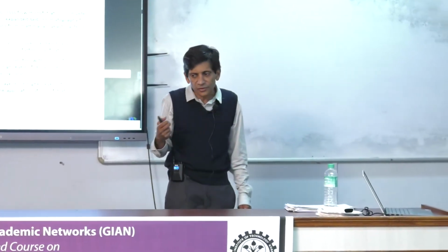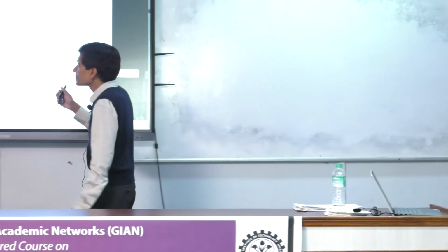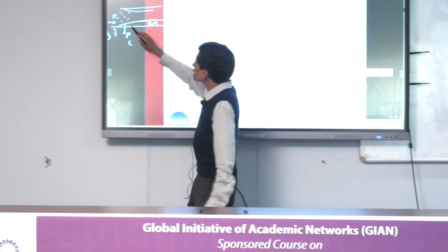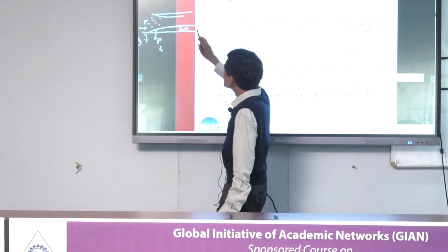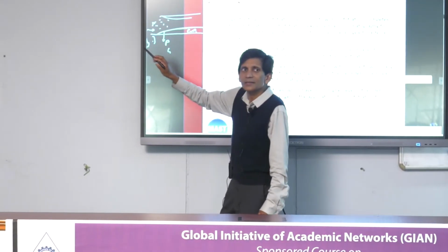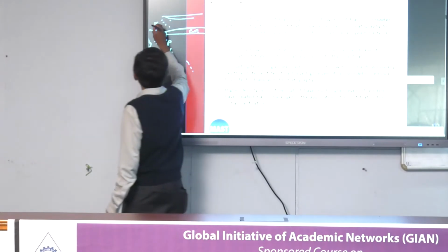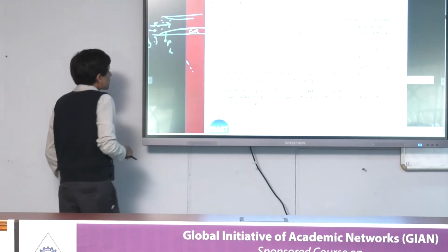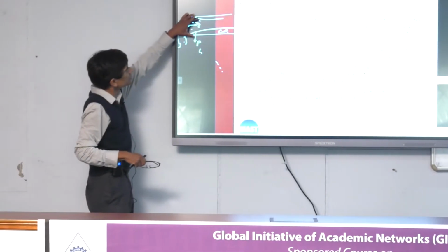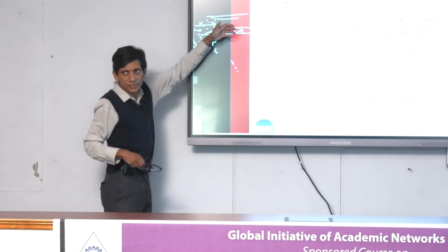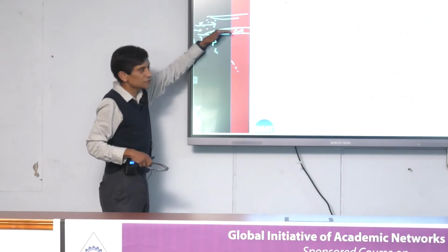Now in tangential flow microfiltration, we said that the growth of this concentration polarization layer is going to be limited, right? It's limited by the fact that you have fluid flowing this way. So if you think of it, this is my original membrane. I'm pumping this way. I'm starting to get a cake layer formed on the surface.